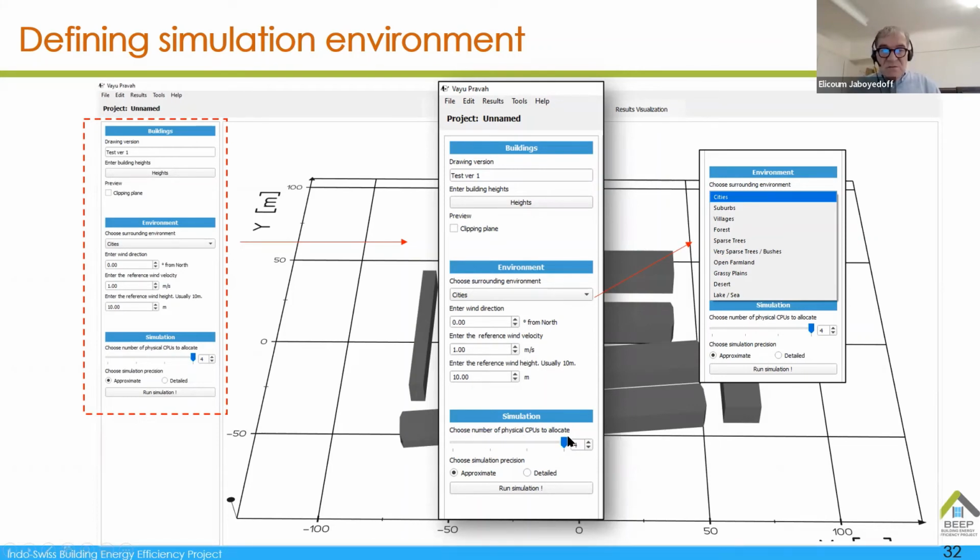Suppose you want to work with your machine and you have 4 CPUs. If you select the 4 CPUs, then your machine will run almost 100% with all the processors, and it will be more difficult to use it at the same time. It may make it so slow to react. So if you want to keep some margin to work, you can reduce from 4 to 3, and then it will use only 3, approximately 70–75% of the total power of the machine, so that you still can use it for other office work or Excel or different applications.